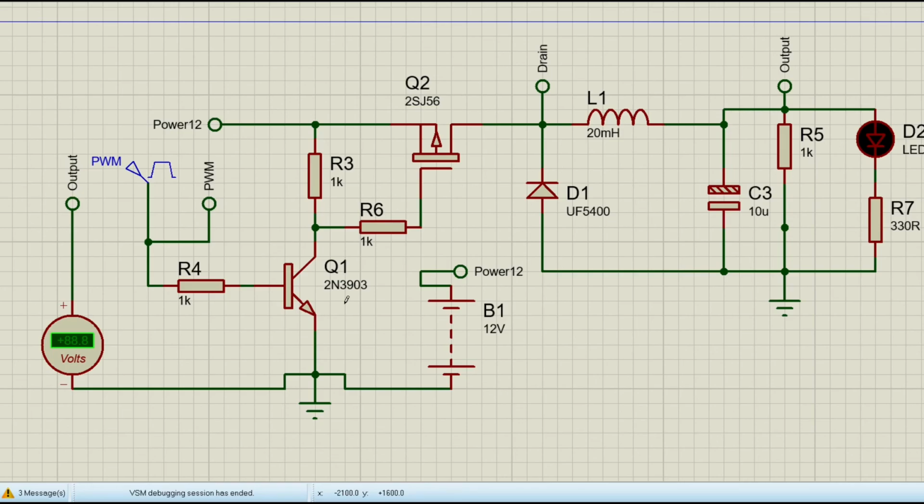So we will generate the pulse width modulated signal from our Arduino, and we will also provide a feedback path from the output voltage to the Arduino, so it will sense the output voltage and it will adjust the duty cycle of the pulse width modulated signal to exactly give 5 volts in case of using bigger loads, and in case of voltage drops, the Arduino should adjust the duty cycle of its signal and also adjust the output voltage, so it will be a closed loop system.